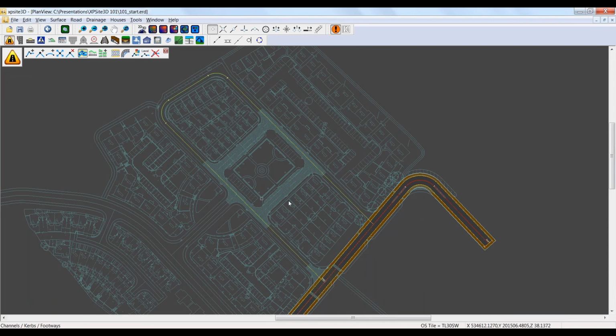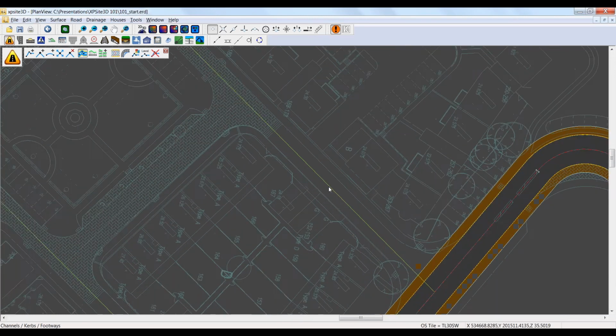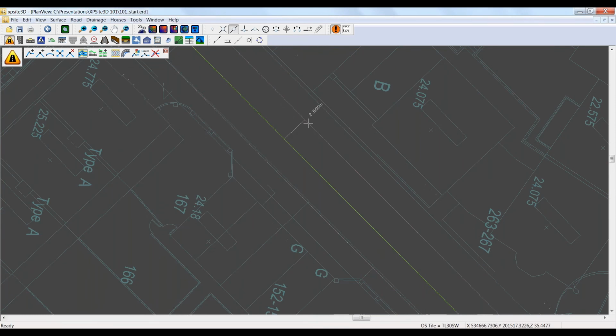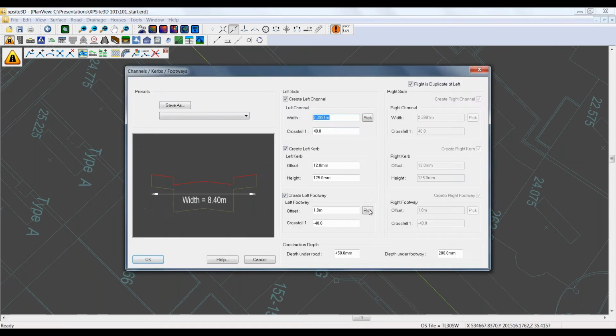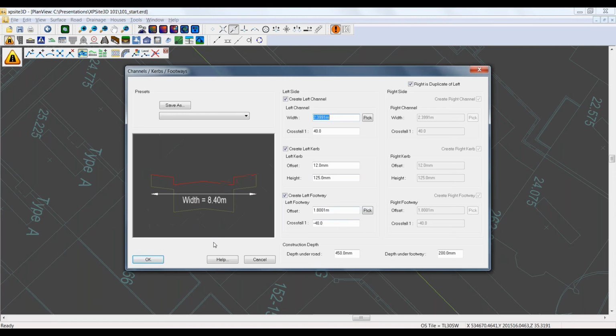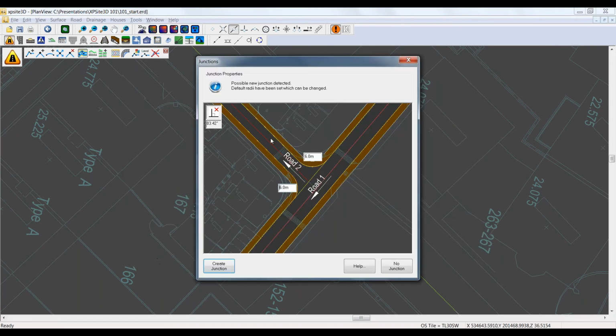And then create the road, again, same principle as before. Click on the road center line, snap to what the architect's done for us, snap to here, and it creates that second road. Okay. Now at this stage, it's identified that what I describe as my minor road 2 is joining to my major road number 1.